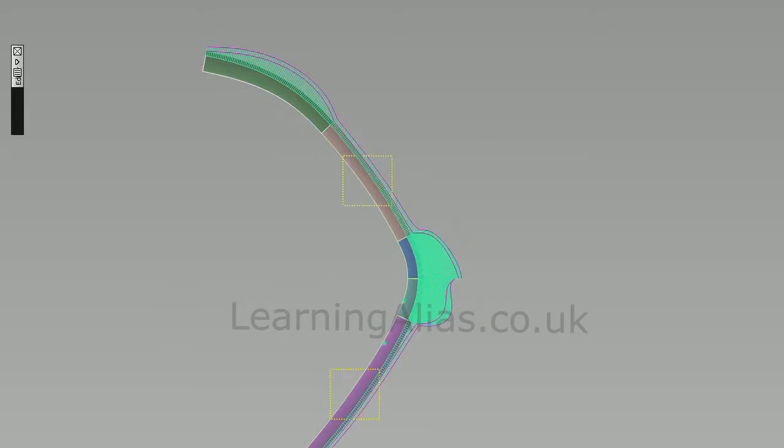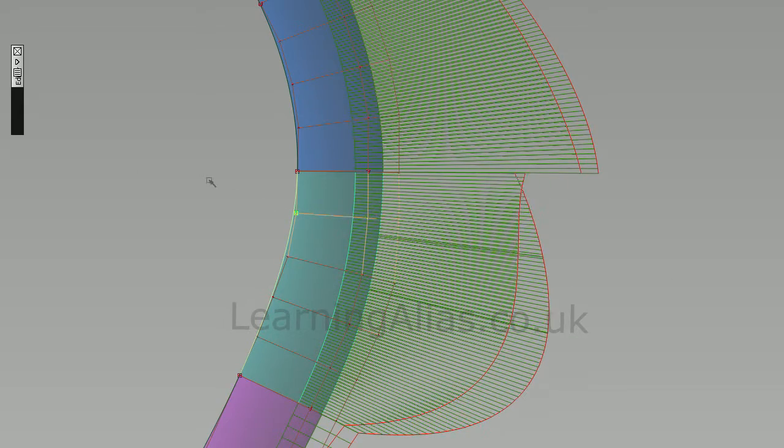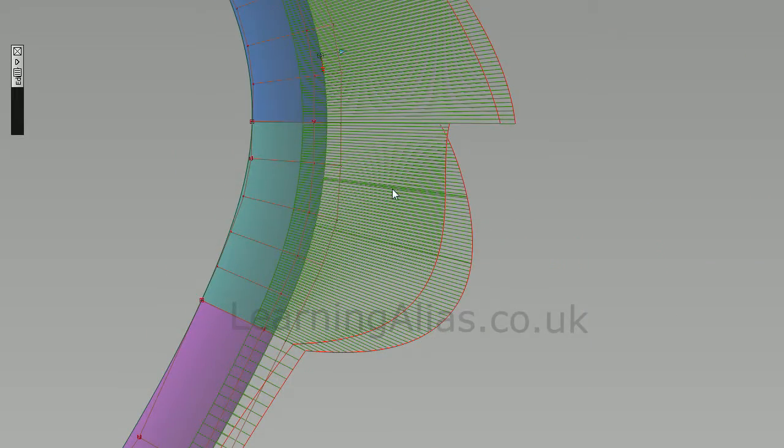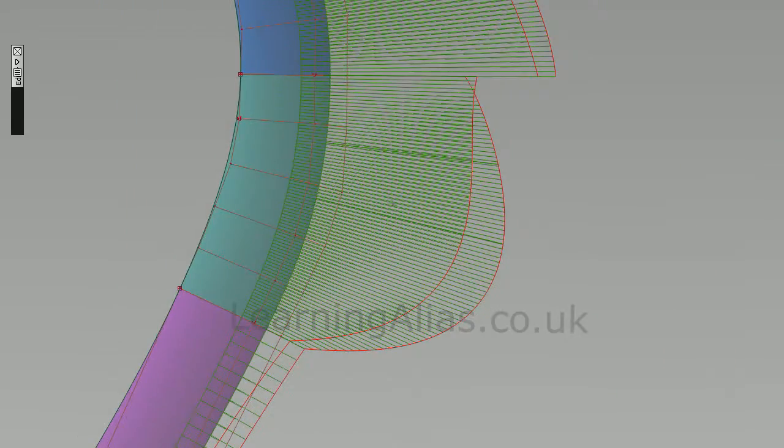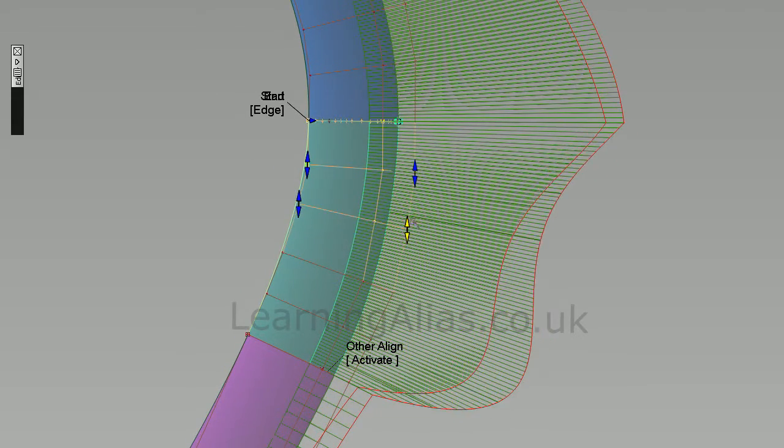So now what we can do is turn the controls for these surfaces on and delete their history. Then you can see, rotating the holes or pulling CVs in XYZ direction or NUV direction, what kind of effect it has on the combs. So the comb is showing us that we've lost G2 continuity, so we'll realign the lower surface with the upper surface.